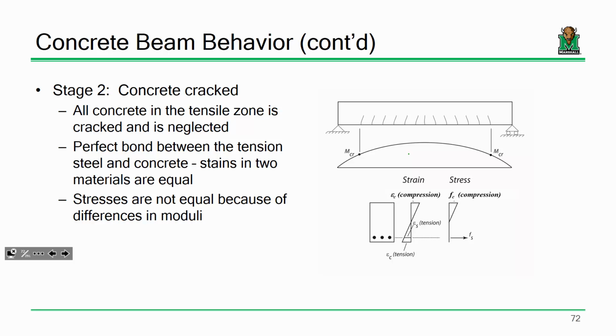Does that make sense? Tell you what, next time I have a video that I can show you that might help clear it up. What ends up happening is when you start loading a beam, you start to develop these flexure cracks that look something like this. So in this region, let's be clear, the concrete is separated, and at this particular point, the concrete cannot resist any tensile stress. But these regions of the beam are still gripping onto the rebar. Keep in mind, when you see rebar, it's got those ridges on it for a very specific reason. They're taking over resisting those tensile stresses.